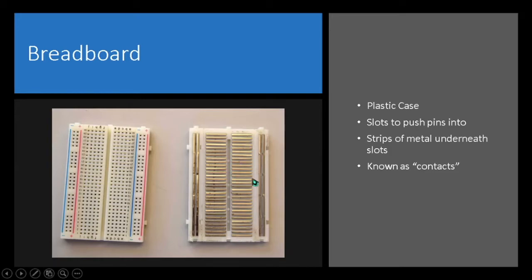So this is really useful for components. So if you have, for example, an LED and you want to put it on your breadboard, you can take one wire to the 5 volts and one wire via resistor to ground. Don't worry, this will all become clear soon in the next video, where I'm going to teach you the Arduino IDE and our first major project in terms of programming and hardware.